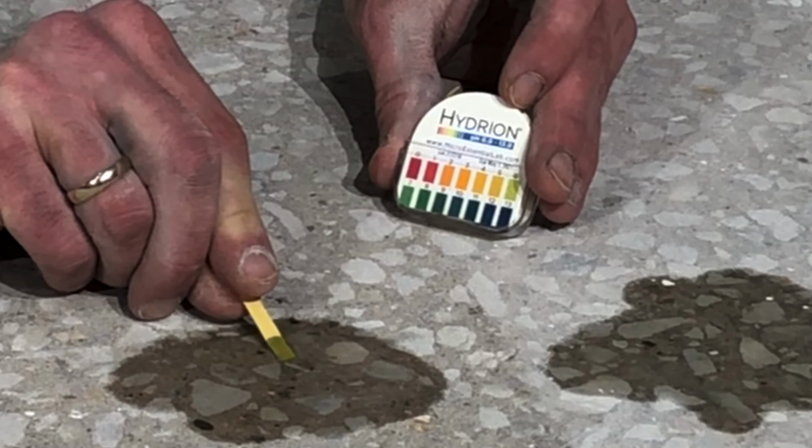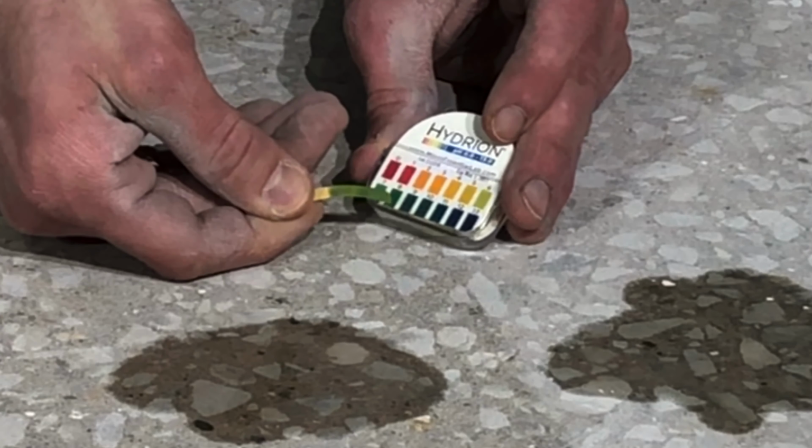So a pH test is very simple. It's just distilled water and a pH pen, which is the easiest way, but you can use an appropriate litmus paper or something. And it's going to give you a scaled result that guides you in a direction. It is also utilized with moisture testing, specifically calcium chloride tests. But if you don't do that test and all you're checking is moisture, you may be missing something because there could be a contaminant there that's the problem. And the moisture by itself is just another issue. So you're kind of forgetting something.